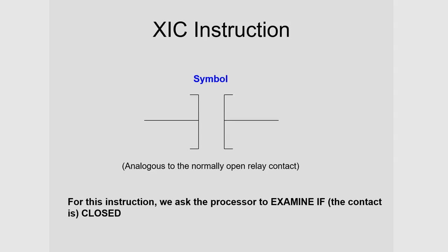In the input image table, you had cells, and for us there were 16 cells because the PLC simulation software that you use is word oriented. That word is 16 bits, so for each bit there's a cell in the input image table. Those rows are really registers, and the register can hold a 0 or a 1.